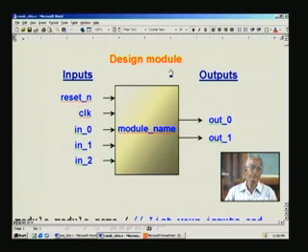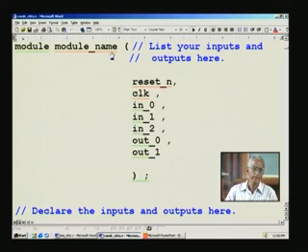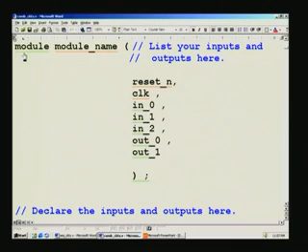And now how to code this in Verilog? So what you see is you start by writing on your paper this block and then go on to code it, and the way to code is right here. See, first we said module name, and that is what appears here, and before that we had to say it is a module, and naturally the whole thing is identified by this module name, which is particular to your design. And module is a keyword in Verilog to identify that there is a module here. So there will be a module here and a corresponding end module at the end, which we will see towards the end of this piece.